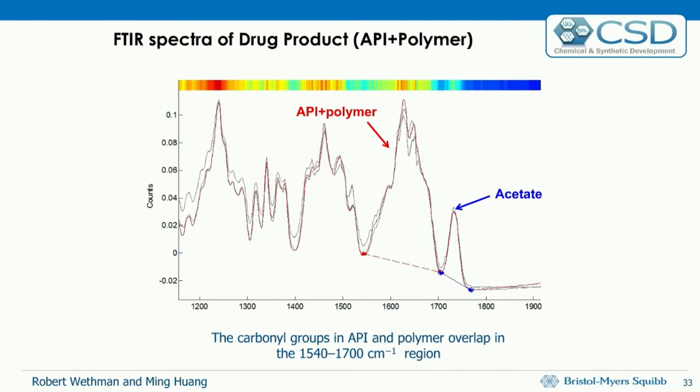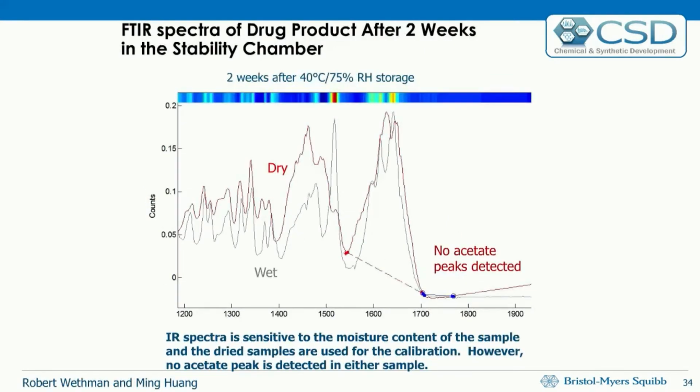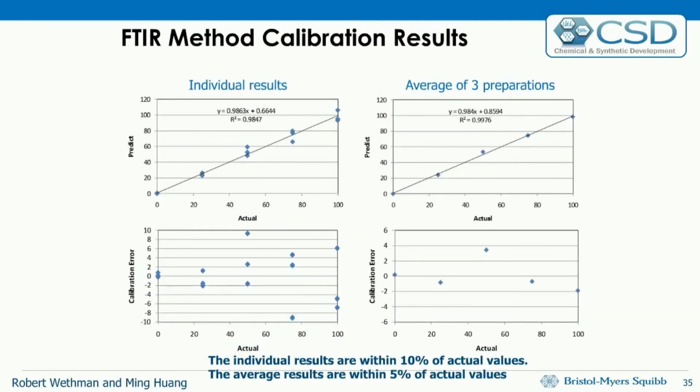after in the drying chamber, and so we're doing small-scale development work, we're looking at the moisture content, we're analyzing what acetate is there, and at a particular temperature for a period of time, 40 degrees, 75% relative humidity, we ended up losing that acetate. So that's going to give us an indication of what kind of conditions we need to maintain. So you want to build a model off of this.